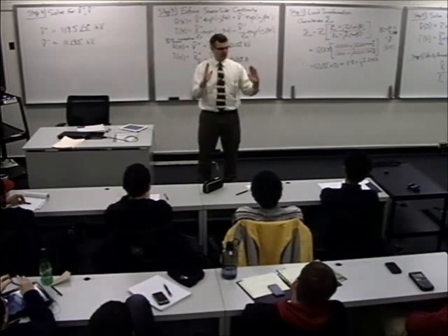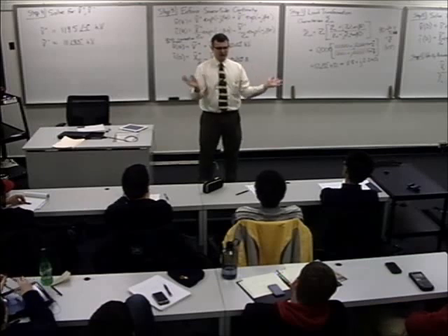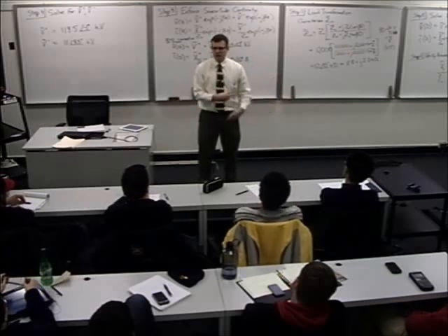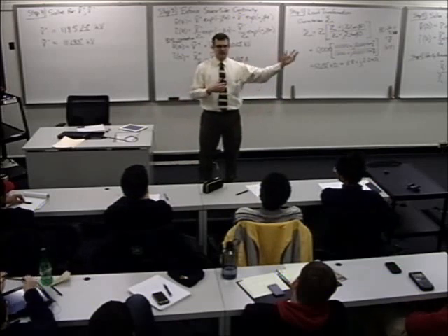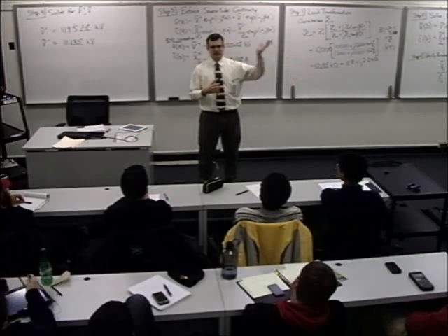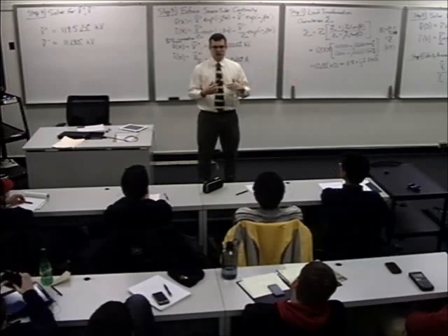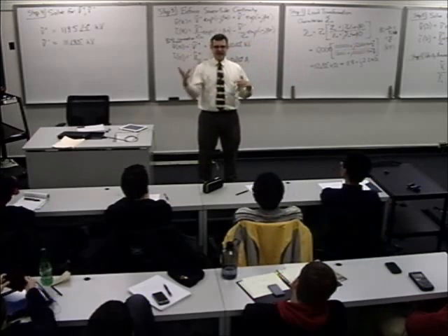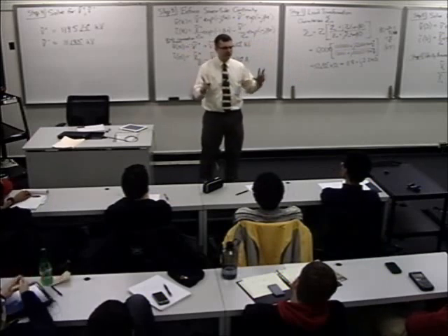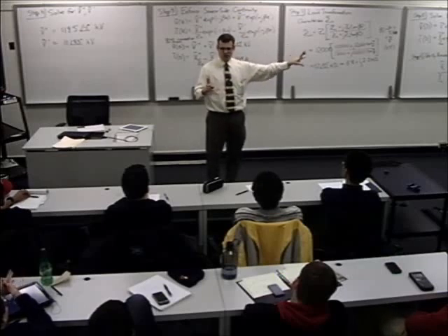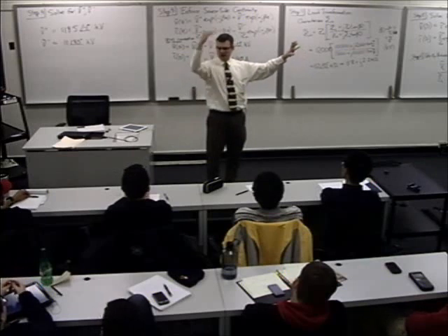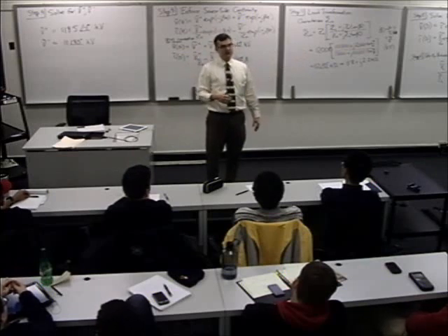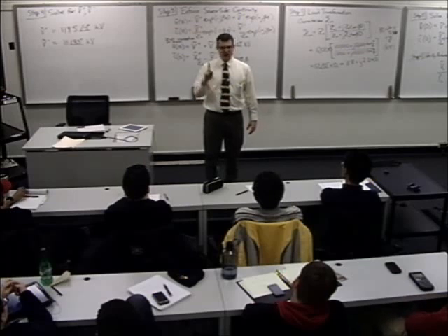We still have, at this point in the class, a lossless transmission line. So despite all the craziness going on to and fro on the line, none of that power is being absorbed. It's transporting some to the end of the line, and some is going back to the source. We just figured out how to calculate the net power delivered by the source. That should be equal to the net power delivered to the load, 1/2 the real value of voltage squared divided by impedance. That's yet another way to check that you did the problem right.